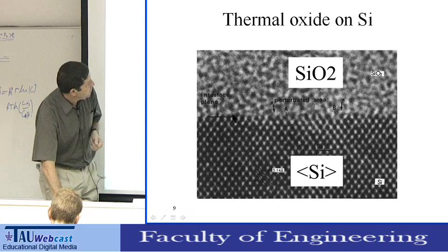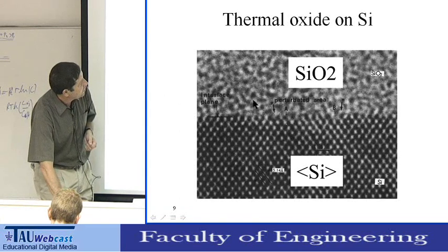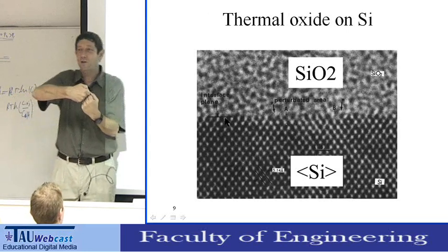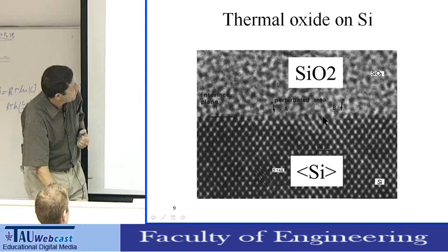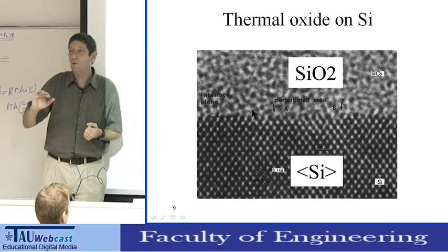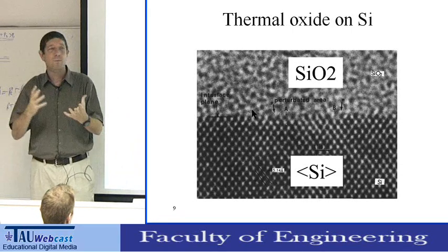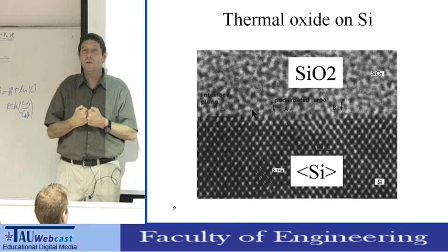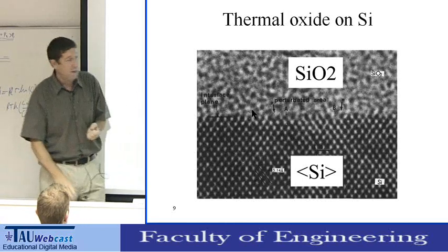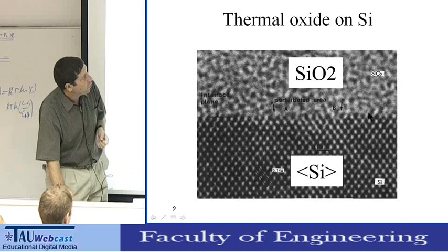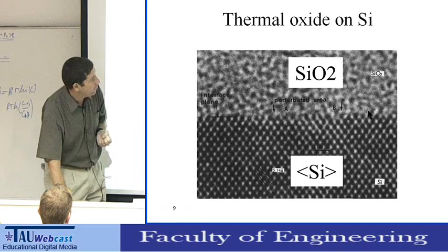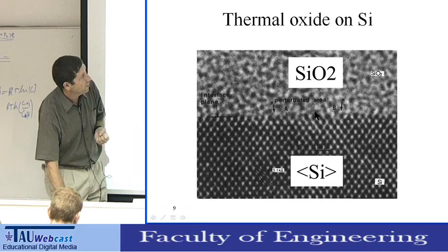Another interesting effect you see at the distance is that, although in SiO2 it is difficult to see the atoms, every atom in the oxide kind of matches every atom in the silicon. So on the surface, there is a very small number of free electrons, of unbonded bonds. Bonds which are dangling, which are free. And this interface is not only very stable, it's also electrically stable. It's a very small number of bonds which are not bonded.